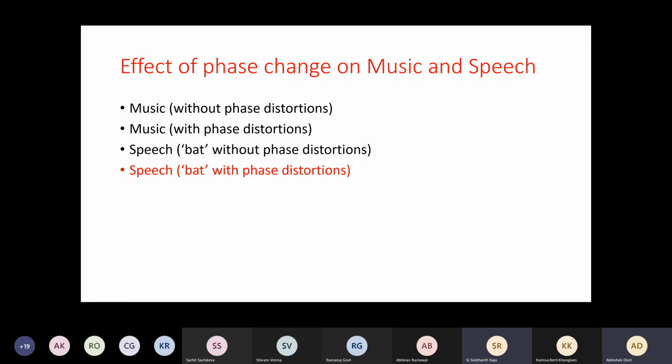Sir, what is the utility of all pass filters? If it allows every frequency to pass, then how is it a filter? We will see the utility of an all pass filter next time. But suppose you have an image and you pass it through an all pass filter, the kind of filter that we have shown. The image gets completely distorted. You will not have any sense of that image left, because images are very sensitive to phase distortions.